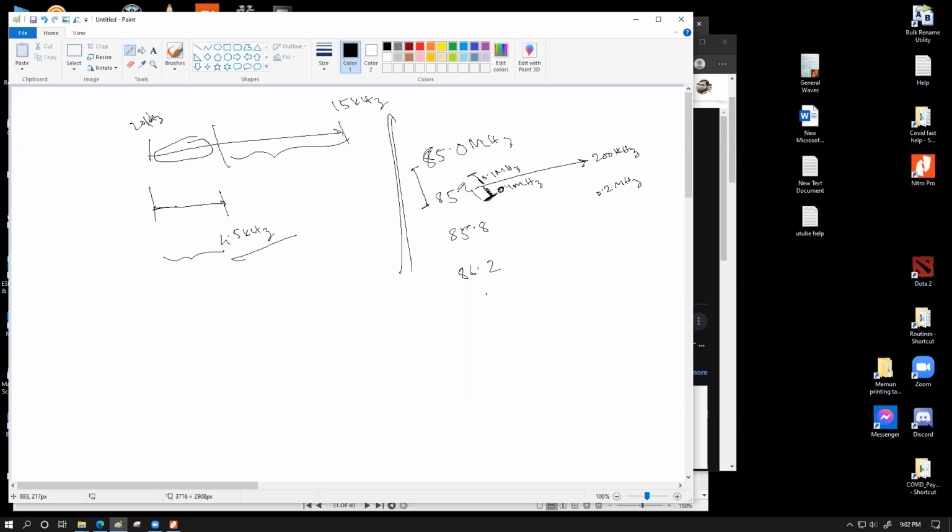So the total maximum frequency of this radio station 85.4 can go up to 85.5. The lowest it can cover is 85.3. Whereas this one can have a highest of 85.1 and this one can have a lowest of 84.9. That's the variation we're going to work with, because 200 kilohertz was the bandwidth, which means half of it was on one side. This leaves us a forbidden gap kind of thing.